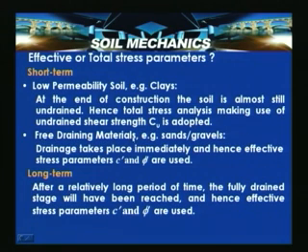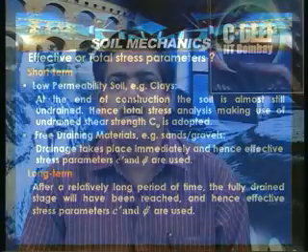In case of free draining materials, that is sands and gravels, drainage takes place immediately, hence the effective stress parameters C dash and phi dash are used. So even for the short term stability conditions, if the material is sand and gravel, then we use C dash and phi dash. If the material is low permeability, as the drainage will not occur, the total stress analysis is used for the purpose of the analysis.